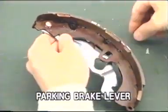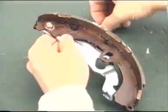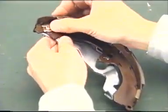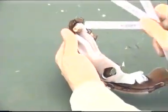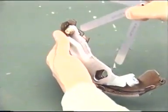Install the parking brake lever temporarily to the rear shoe using a new C washer. Measure the clearance between the brake shoe and the lever using a feeler gauge. Replace the shim if not within specification.